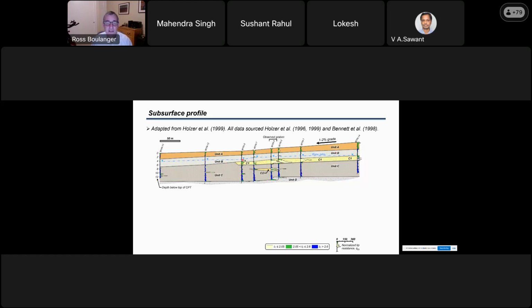And this upper layer here is a clay layer where it's below the water table. It's actually weaker in this range. And so the undrained strength of this clay layer is important too. This hatch zone right here is called the graben. This is where the ground settlement occurred. And downslope of it, things were moving a little bit downhill.